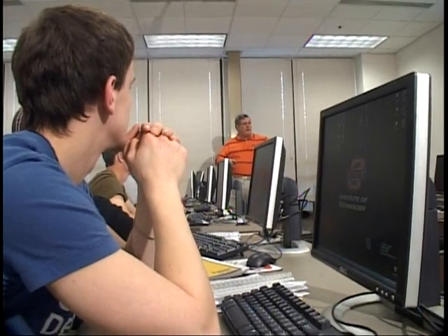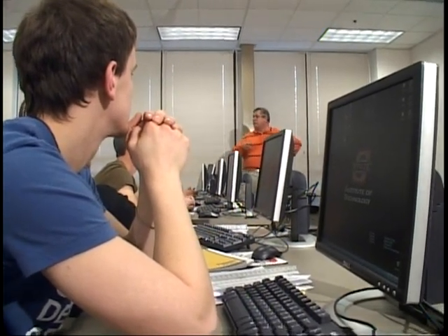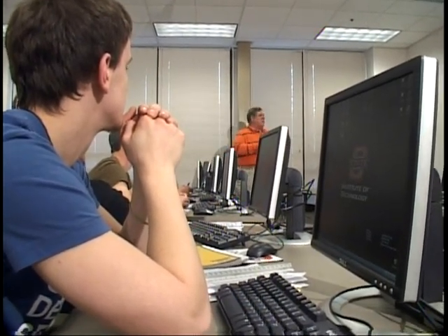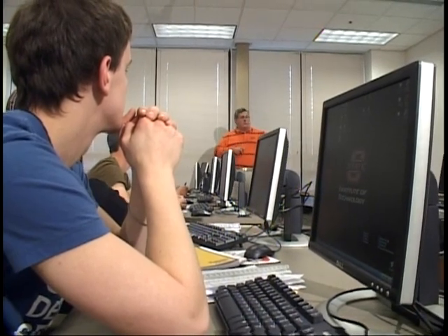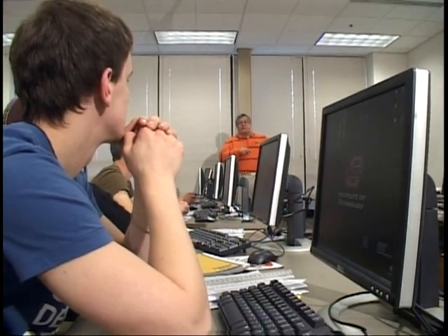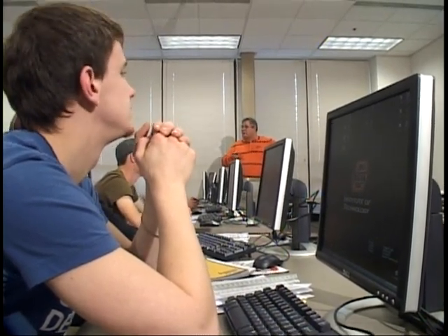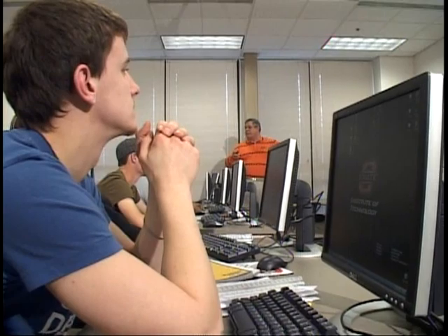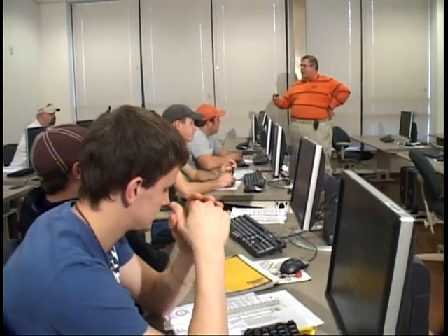Okay, now, something I do and most surveyors do is when you perform a survey and you generate your survey drawing, what I measured in the field, I called it measured. Some people put survey. And then underneath that, I showed the record bearing and dimension. In my particular case, I say it's plat number 6065. Some people will just put by description. Either way is acceptable. Up until a few years ago, abstractors went crazy.